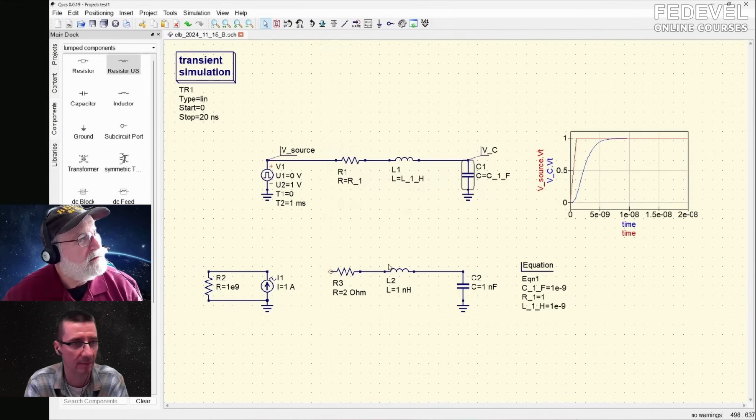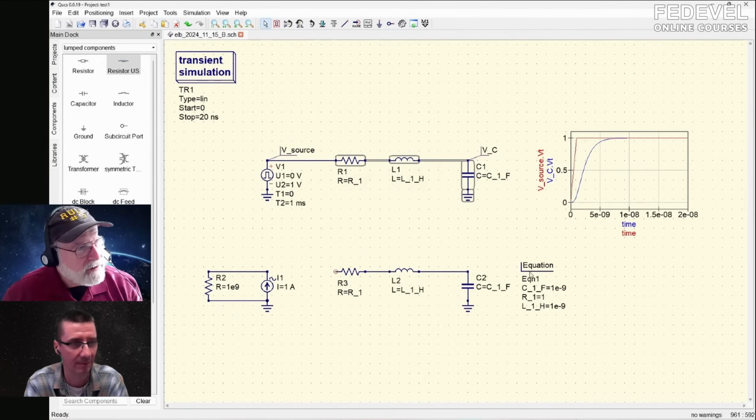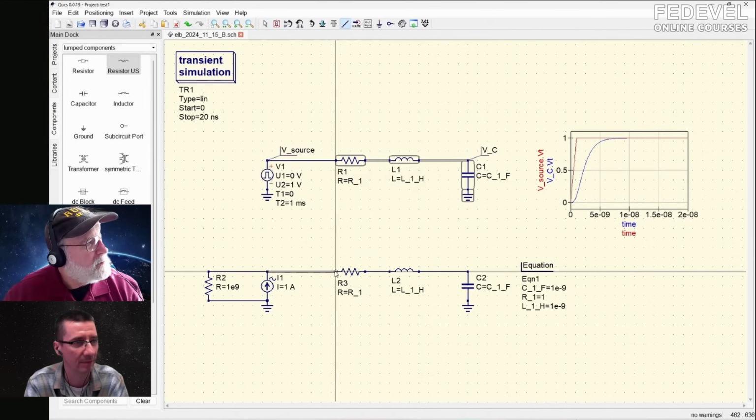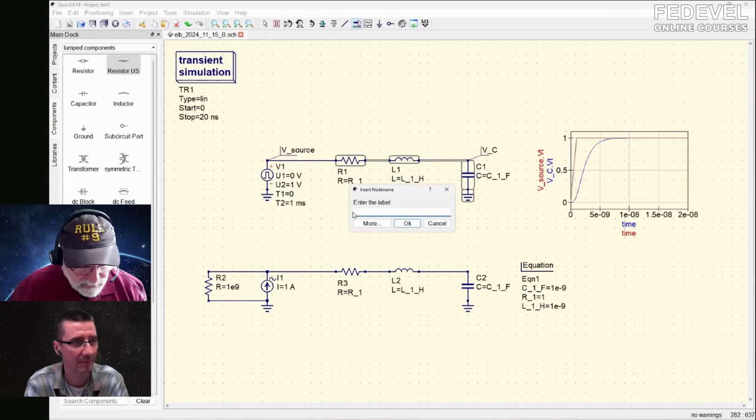If you don't have units here, that means they're SI units. Oh, you know what? I don't need that. I can just grab this guy now that he's all created. So I'll grab him, and now I change the parameter values once over here, and that's going to ripple into both of these. So look at time and frequency. Now we're going to connect them up, and now the voltage here that I measure in volts is literally the impedance looking in here in ohms. So let's grab our label here, and I'm going to call this impedance of circuit 1.